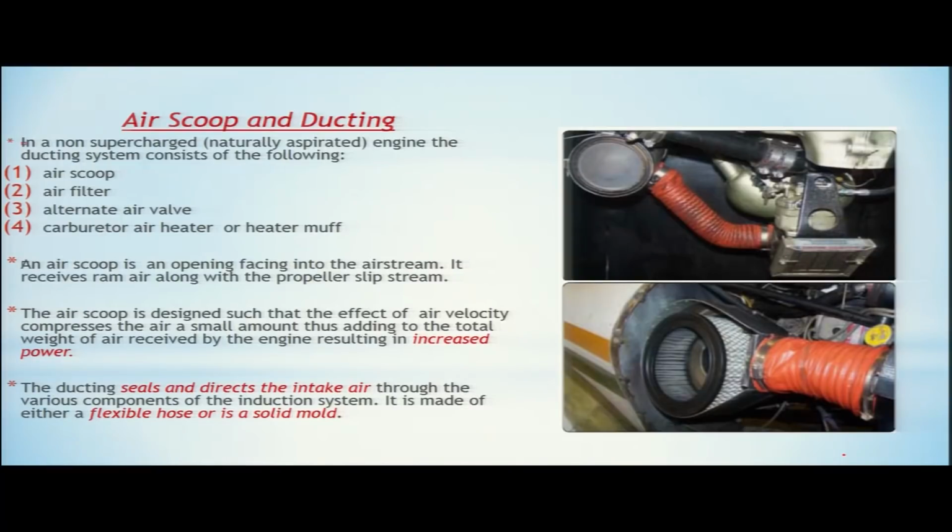So, in this picture you can see this is your flexible hose, and the air is being directed from the scoop to the induction system through this flexible hose. So, this ducting can be either a flexible hose or a solid mold. In some of our engines, we will show you the induction system, a flexible duct as well as a solid mold duct.